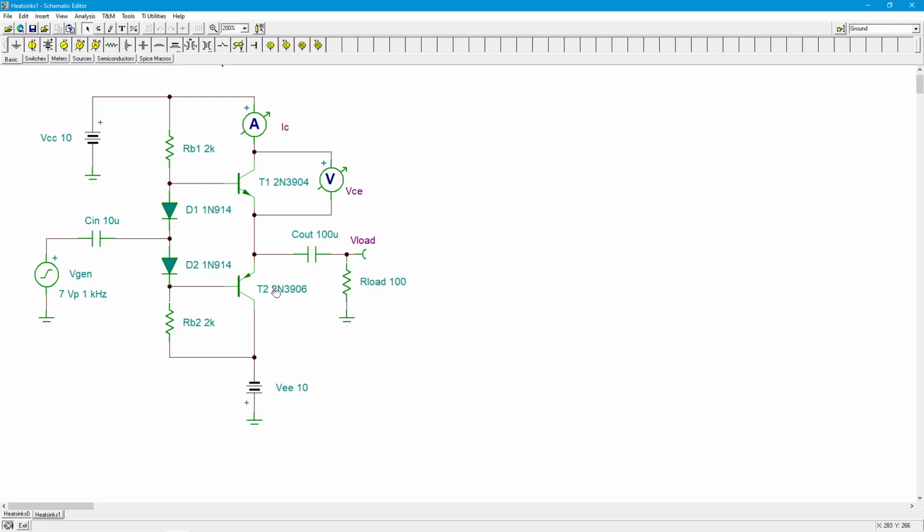And that's, again, another reason why they have to be electrically isolated. Because this collector is sitting at some negative voltage and this collector is sitting at some positive voltage. And if they're both sitting on the same physical heatsink, you just shorted out both your power supplies. But generally speaking, it's a lot easier as far as mounting and so forth if you take your power transistors and just stick them on one big heatsink rather than trying to dole out individual heatsinks. It all depends on the application. So those are other things to consider.